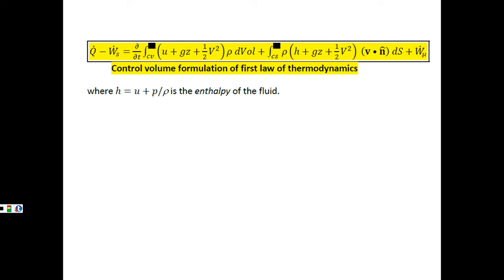And then we had our Reynolds theorem, which we could derive with respect to our variable E as our system variable, which allowed us to come up with this formulation, which considered the change across that control volume of our element and what was happening inside that control volume, as well as what's coming in and out of the system at the control surface. And then we had this additional viscosity work term that we had to factor in. Okay, so this was really considering the energy in the form of heat capacity. It was thinking about it in terms of potential energy with the gravitational term and kinetic energy in terms of our velocity squared term.